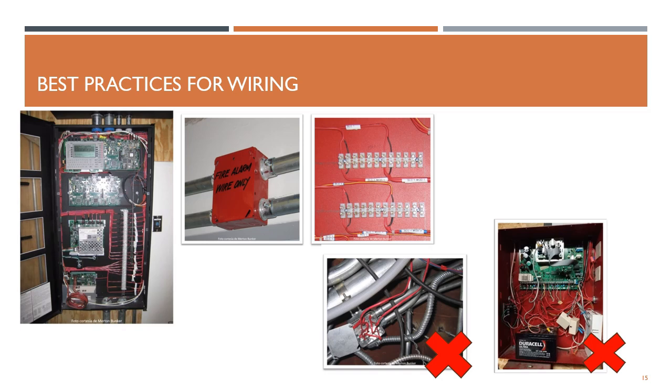Let's now move on to the connection in the boxes and on the main fire alarm panel. In the first picture on the left, we see a correct installation and connection and cable passage inside the fire alarm panel. You will be able to see that we use splicers for the installation.